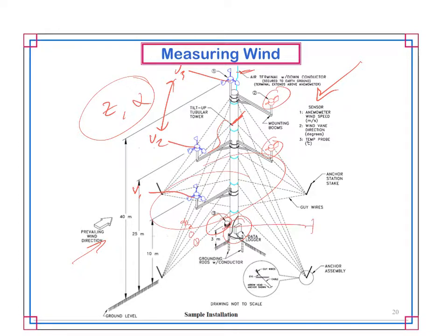But another important thing is the little device over there that measures temperature. Why do you think temperature is important? You can pretty accurately predict what the temperature is going to be at a particular location because it does affect the density of the air. So the lower the temperature, the higher the density, so you can get improvements in power. Why would you want to know what the temperature is?